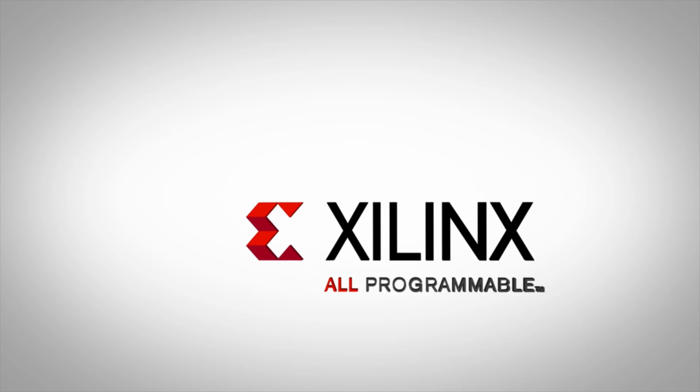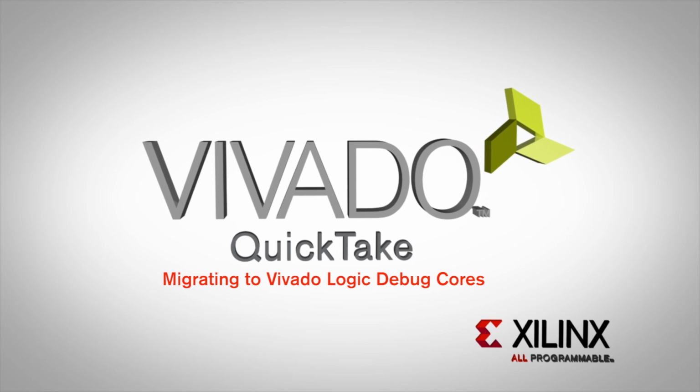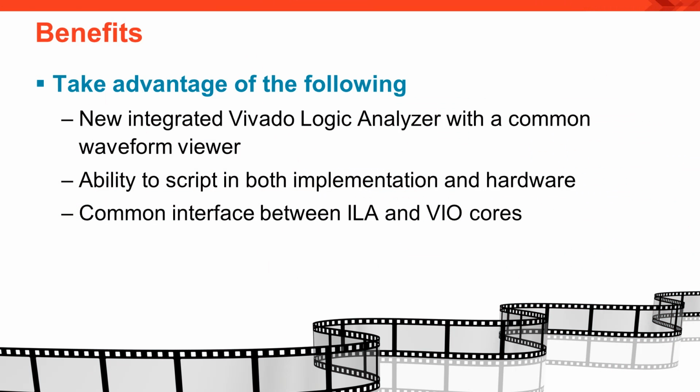Hello and welcome to this Vivado quick take on migrating your design with legacy logic debug IP to Vivado native debug IP using the integrated Vivado logic analyzer. Migrating to Vivado lab tools will enable you to take advantage of key features that are not available in ChipScope Pro. For example, you can take advantage of the new integrated Vivado logic analyzer, which includes scripting capabilities and a common debug interface between the integrated logic analyzer or ILA and the virtual input-output or VIO cores.